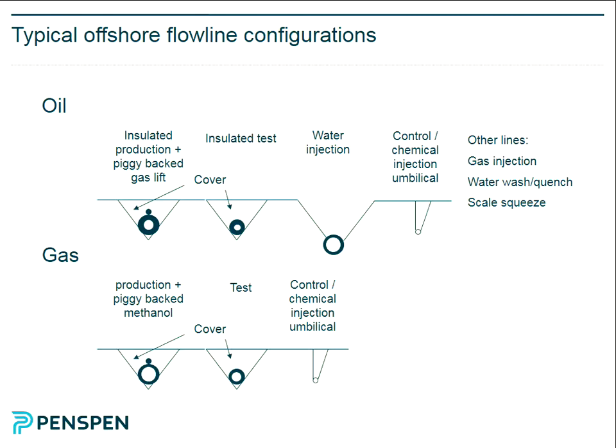So if you have multiple wells, the idea is you produce from one well on its own through the test line, and that goes to a separate test separator. And then the test separator will give you the oil, water, and gas coming from that specific well. That will allow you to manage the production from your field, so you can tell the difference between the different wells. Other ways of doing that are to use subsea multi-phase flow meters. So it's possible you could dispense with that pipeline by having a flow meter.